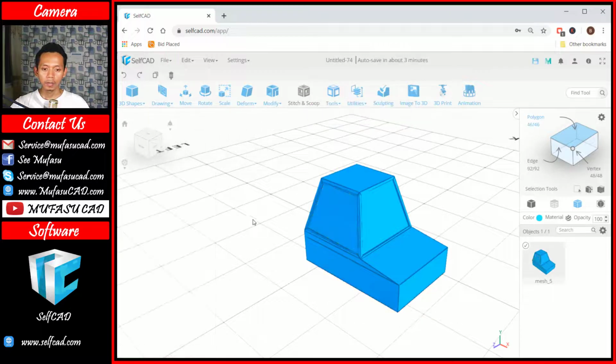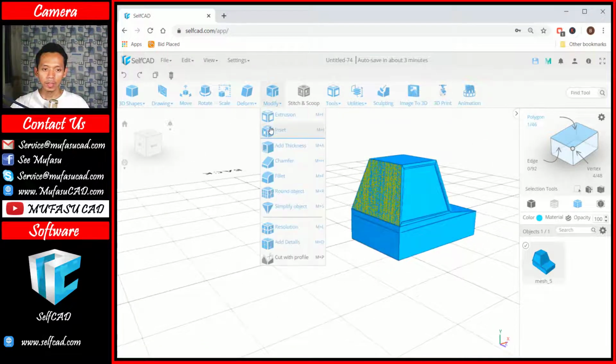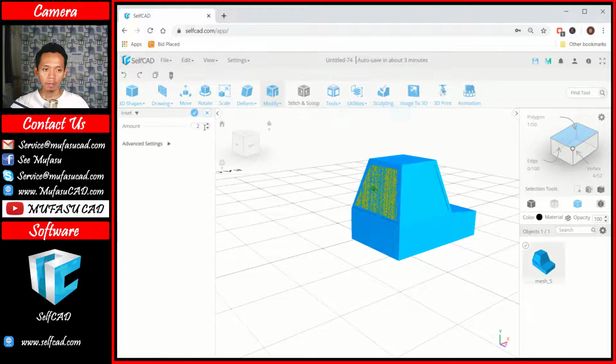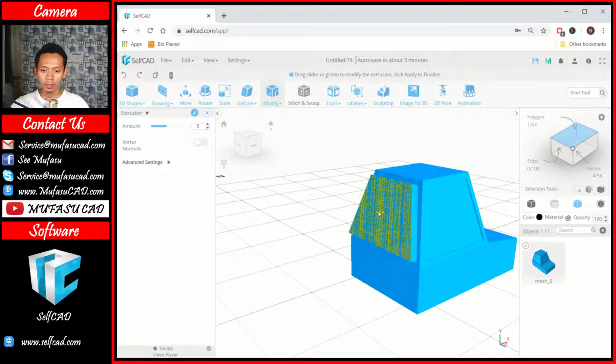Okay, we create again the last at this point. We use the insert tool, set amount 2. Use insert again with amount 1. And the last we can use extrusion to extrude into this point.